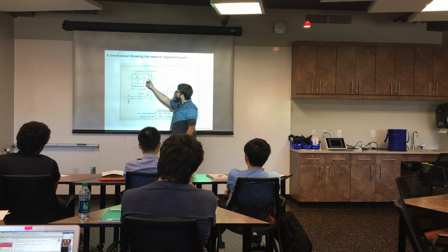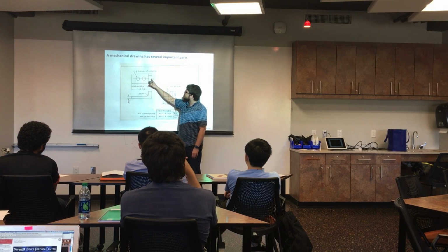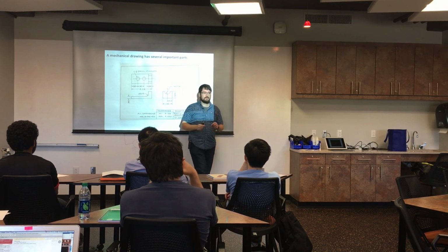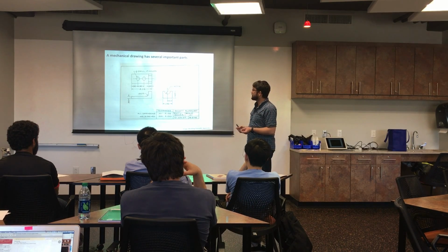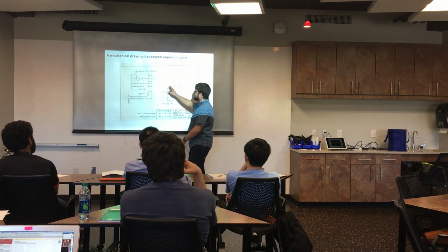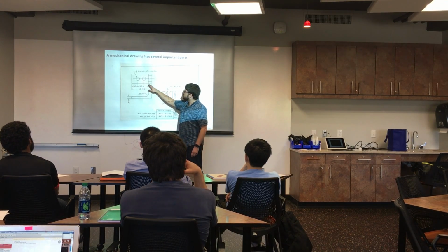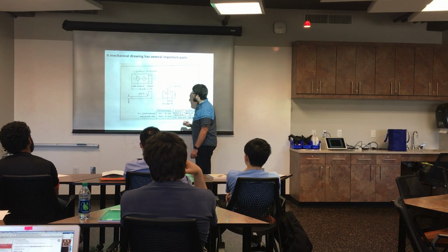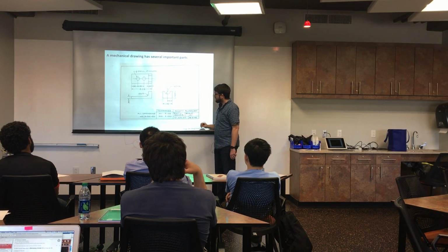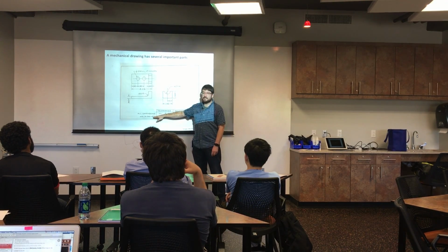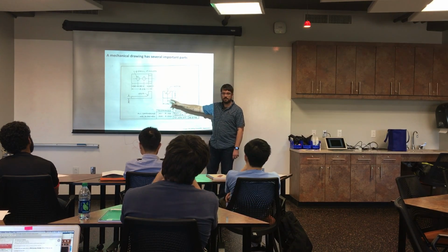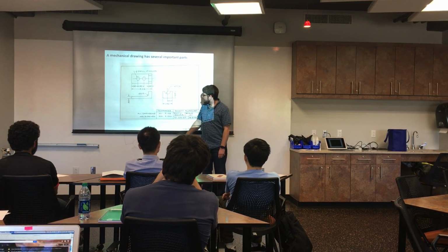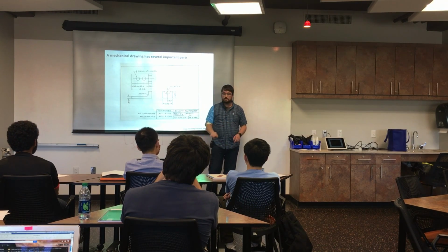These lines here that are generally thinner and broken are centering lines. So they're not a physical thing on the part. It's to help the drawing and show that indeed those holes are along the center of the part. These dimensions are all very nicely done. We'll talk about how to do dimensioning in a little bit. They say that all dimensions are in inches because you'll notice we don't write the units after the dimensions on the drawing. And there are tolerances.